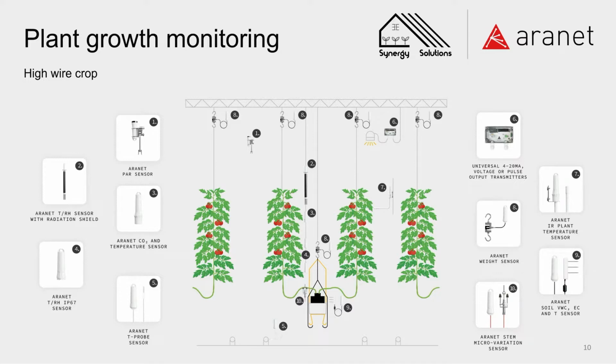And then since we are working indoors and growing indoors, we would like to measure light, and I would suggest that you measure light inside, because inside light will be the one which the plant will consume, and that we do with a power sensor, but I would suggest to use more than one power sensor, and in the best case it's 4 power sensors distributed evenly in a greenhouse, because we see light blockage from the structure, and it is not wise to use only one sensor. Of course you can use a sensor outside.